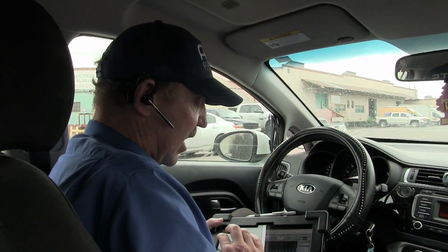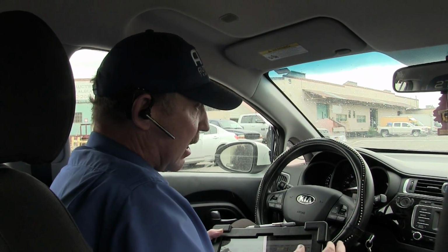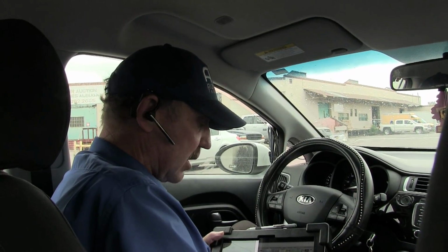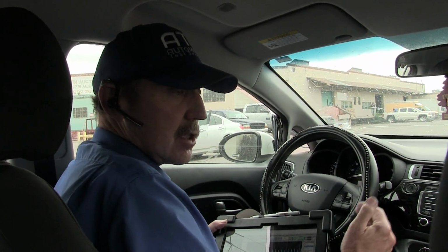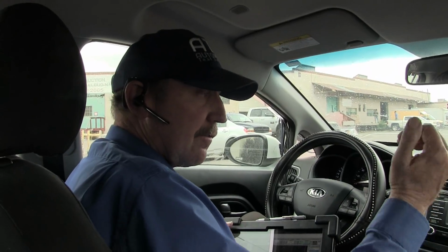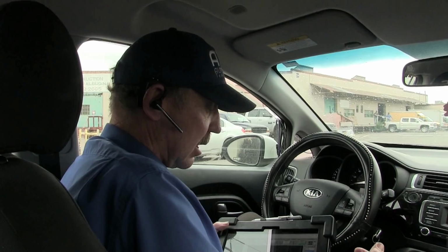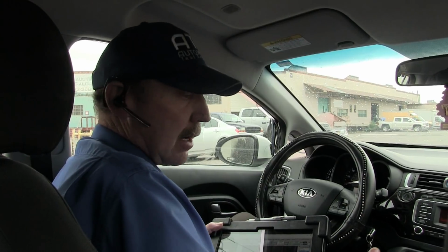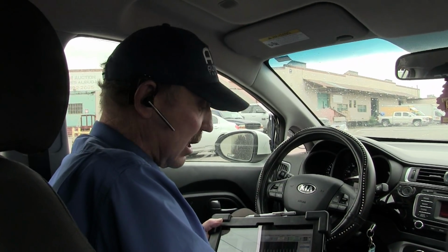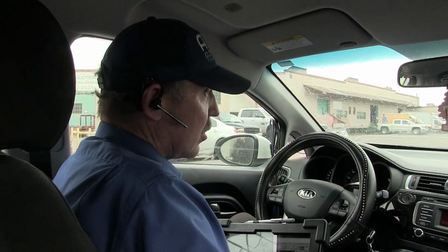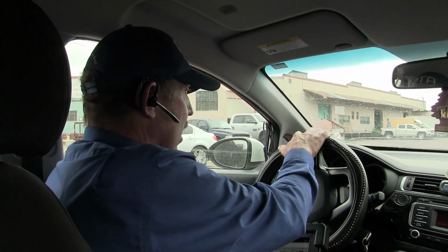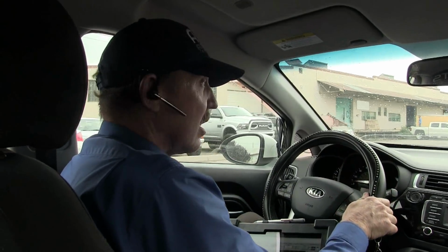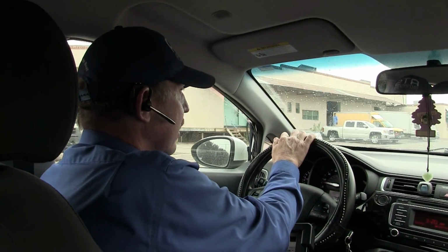And now I know that I've got a restriction, so putting a pump in the car is not going to fix this problem. The pump is fine. There's something wrong with the line. The feed line somehow is restricted. So we need to go get this car up on a lift and make sure what is going on with that line. So we'll go back to the shop, and we need to try to find where the restriction is. We're going to go back over to the shop and talk to the owner and see if I can get a lift to see if I can get it up to look at the line.